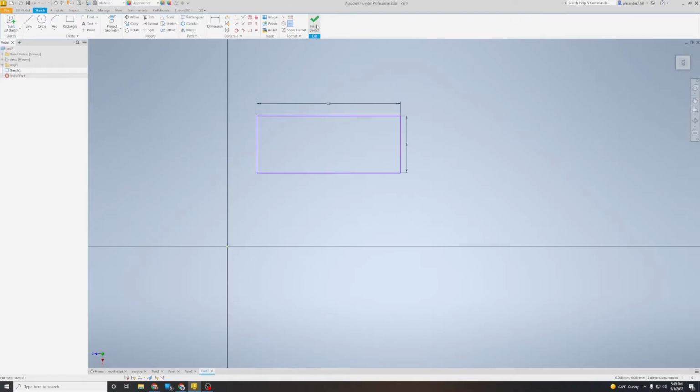That's looking pretty good. The next thing I want to do is I want to make those bumps. If I use the circle tool on the top, these bumps are really aggressive when they get revolved around and don't look that great. Instead, I would like to have my bumps below and just stick up a little bit. But getting that to be even could be a little tricky, and I might not get them all just the way I want them. This is a great opportunity to show you how we can make a construction line.